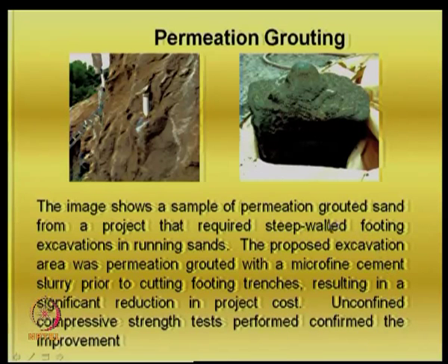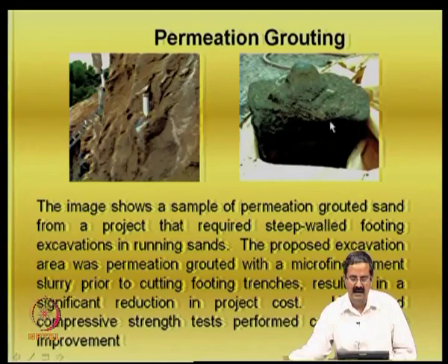And if you test the unconfined compression strength of this material treated with permeation grouting, see, permeation grouting is just a cement slurry except that it has filled up all the voids. So, it can also bind all the particles, and if it can increase the strength in this manner, definitely it is going to be very advantageous. It leads to a lot of improvement in shear strength and reduction in permeability. All these advantages are inherent in permeation grouting.